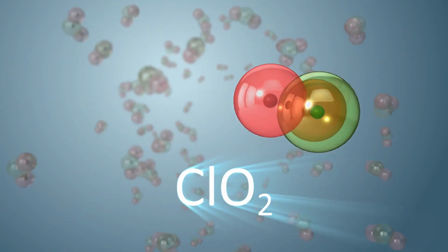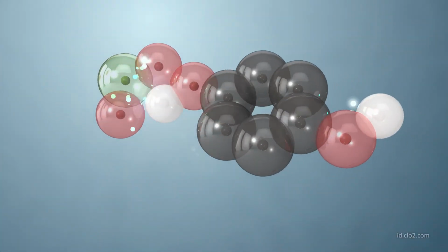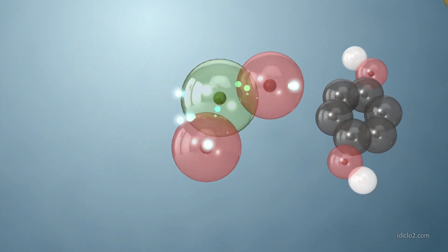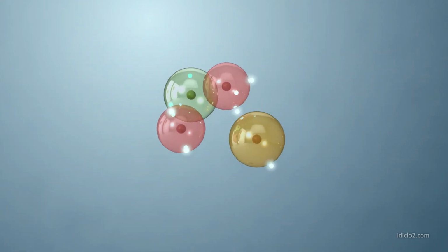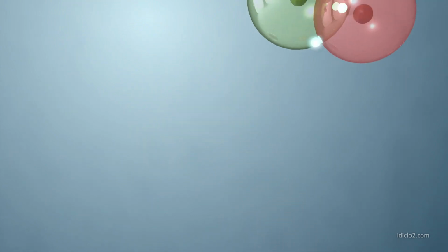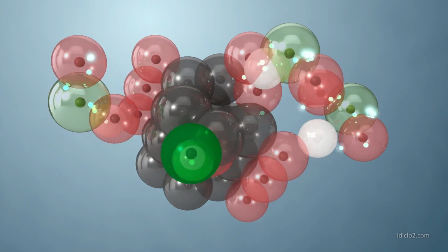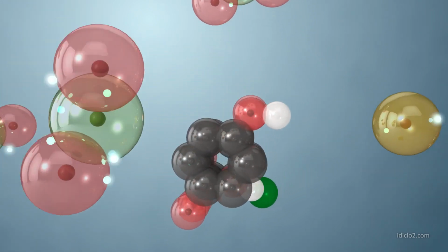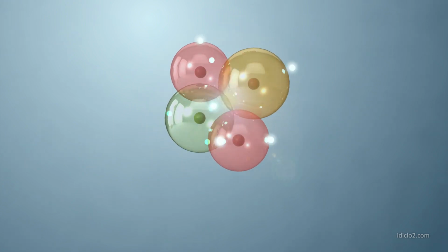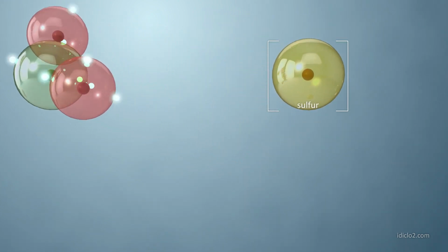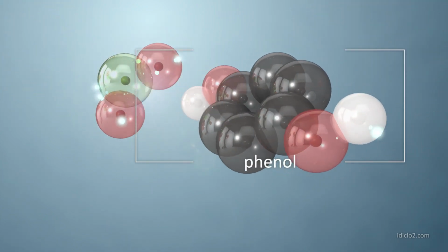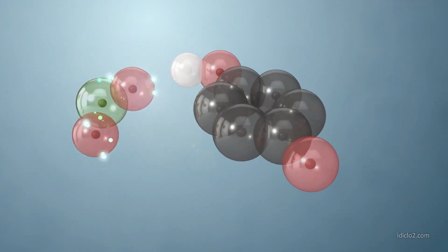Chlorine dioxide functions as a highly selective oxidizer with less environmental impact than other biocides. ClO2 readily oxidizes electron-rich chemicals such as sulfide, iron, manganese, and organic molecules with electron-rich groups. In this reaction, sulfide ion is reacting with ClO2 to form elemental sulfur, or in some instances, sulfate. Most notably, ClO2 oxidizes troublesome phenols to quinones.